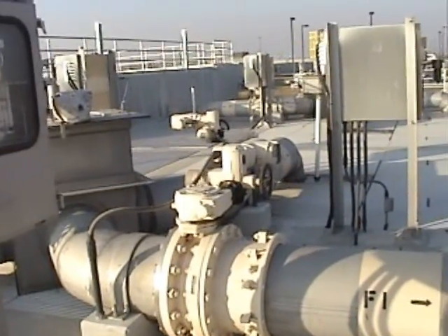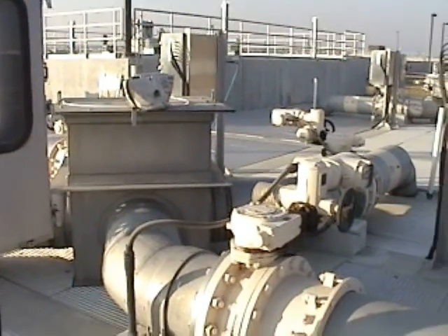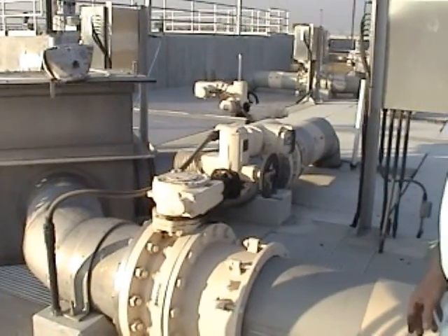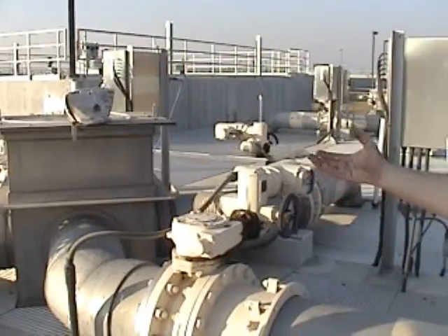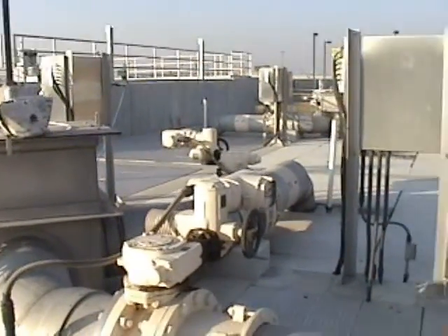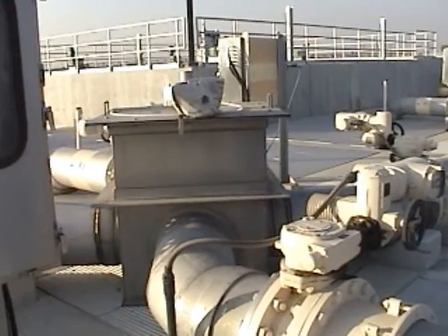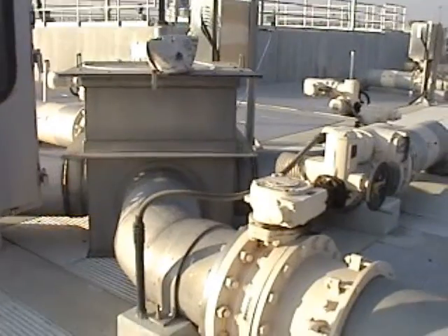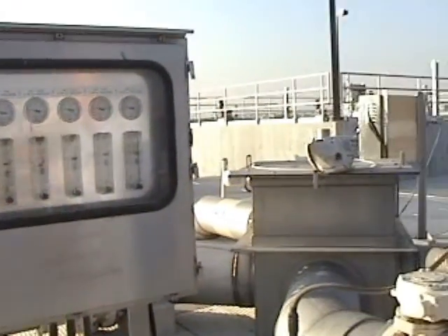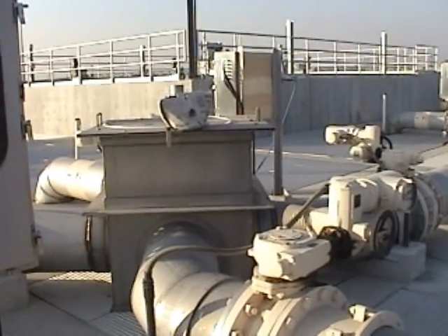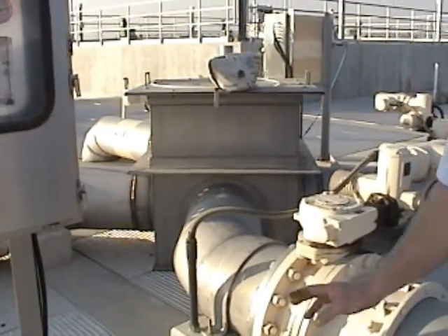Another thing you want to watch for too is we have to look at the flow, where our permit requires us to maintain 5 gallons per minute per square foot or less on the surface of the filters. So you want to make sure that you have enough filters online to cover the flow that you're treating. Plus, if there is a fluctuation and a lot more flow does come in, you've got enough filters online to cover that additional flow. How do you know you are? It's on the screen, on the RP5 effluent screen. It's calculated for us, and I'll show you on that screen. And we have alarms too. If you exceed the filter loading rate, you'll get alarms for that. But usually we run about 12 filters, which is enough to cover far more flow than we'll ever see. Like the rating for this filter system is like 27 MGD, and we're only at 10, so we're in pretty good shape.